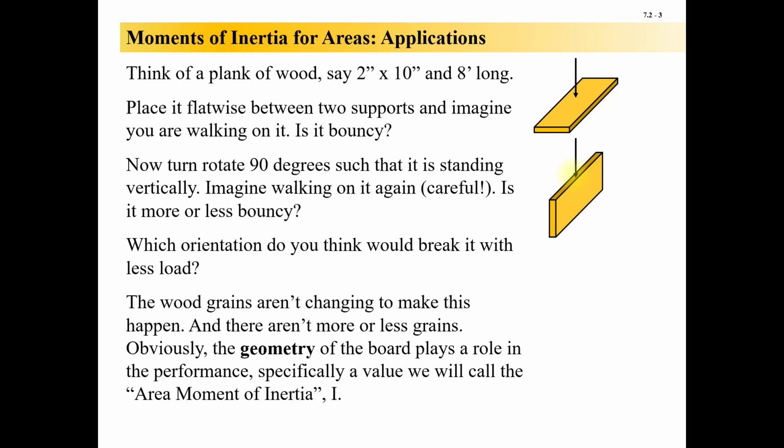And that's not because the wood grains are somehow magically different in one direction versus the other. They're actually the same. What's happening is the geometry of the board actually plays a role in how the board can resist those internal moments and shears that are acting in the board. So that's why it's so important that we calculate area moment of inertia, again, not for statics, but for the next step when you go to apply statics to other problem types.